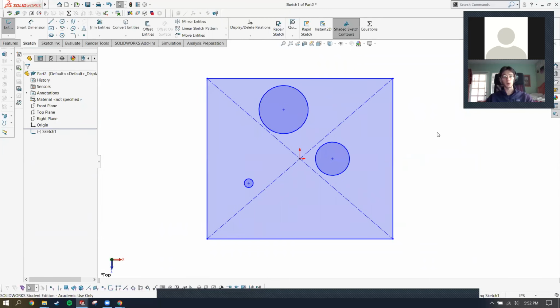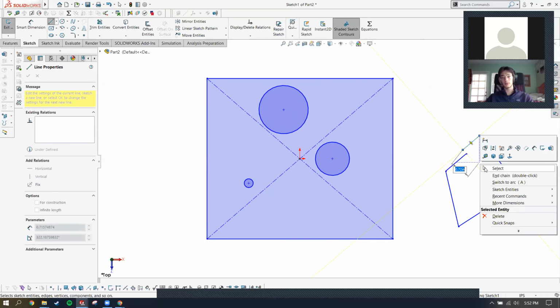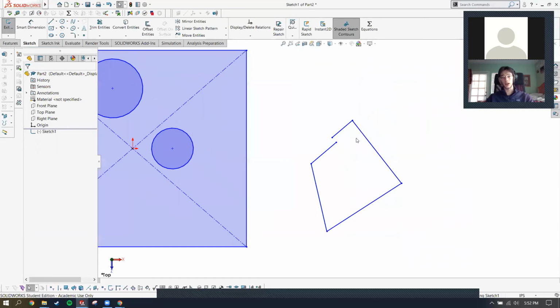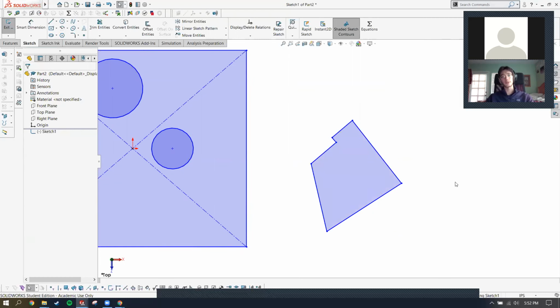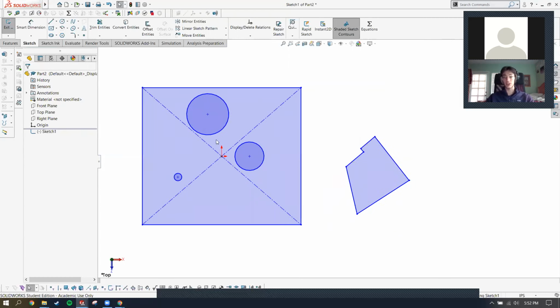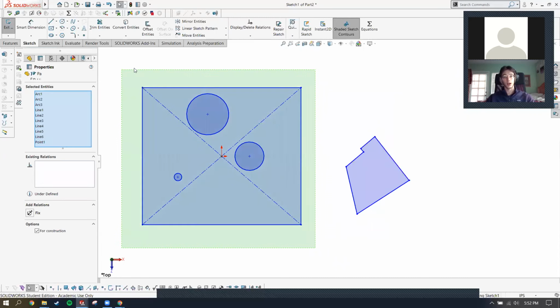So if you're doing a more complex line structure and you don't have it quite completed, then it'll tell you. And that's what SolidWorks recognizes. But as soon as you close a contour, it shows up as a dark shaded region. Now this is helpful sometimes if you're trying to actually make an extrusion or something like that, versus if you're trying to do a thin feature. A thin feature is something that depends only on a line in a non-closed contour. So it uses the line basically to make, I guess I'll show you.